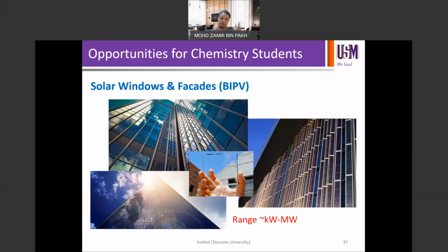So it will be a trade-off between the light that you can absorb and the light that you want to come in, because the more light you want coming into the building, the more you compromise the light absorption, because you will need more transmission. In a solar cell, transmission represents an optical loss.